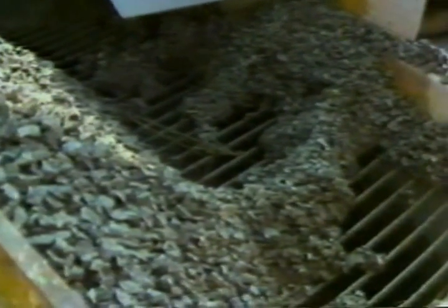The chip fall should be continuously monitored, not only for excessive chips, but for thin spots. If the road coverage is poor, it's likely that the spreader box or screens have become clogged with sand or debris.